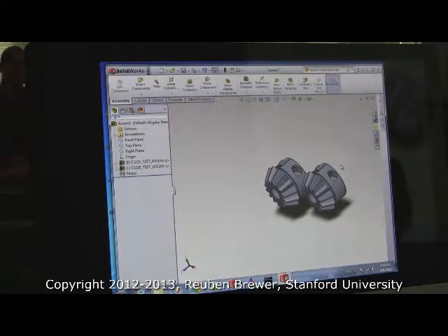It's the same thing with computer programming. You need to structure it intelligently. You don't want to have one assembly and all parts. Anyone know why? You're going to be clicking an awful lot unnecessarily. Say we have 50 of these gears. We can either make one assembly and insert it 50 times, or we can make this assembly 50 separate times, and then every time we say, oh, I didn't want a 12 millimeter screw, I wanted a 14 millimeter screw, we're screwed.